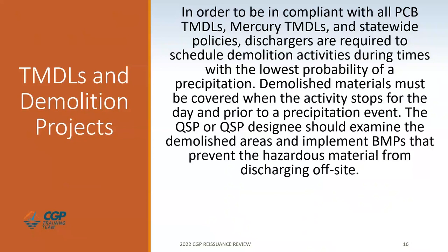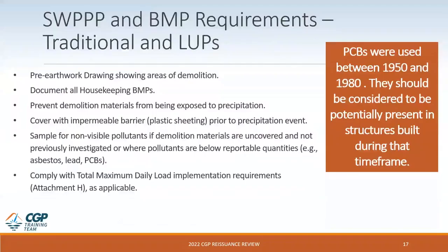Dischargers are required to schedule demolition activities during times with the lowest probability of precipitation. Demolished materials must be covered when the activity stops for the day and prior to a rain event. The QSP or QSP designee should examine the demolished materials for hazardous waste and implement BMPs that prevent materials from discharging off-site. When preparing the SWPPP and implementing BMP requirements, the QSD and QSP must remember that PCBs were commonly used between 1950 and 1980.